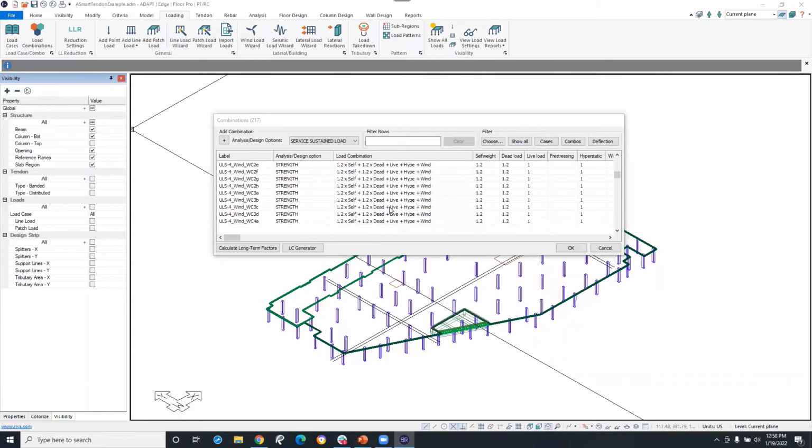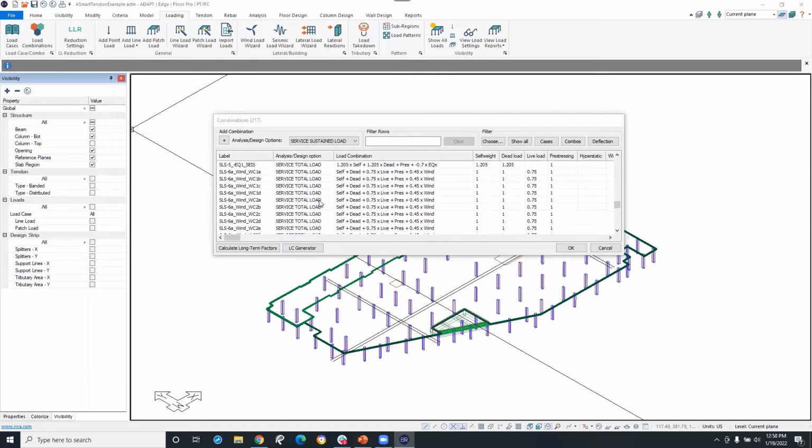And so we can quickly scroll through here, and you can see we start using all of those no code check wind combinations within these wind combinations, and rinse and repeat, right? And you can see all of these appropriate factors applied, and even within our seismic being adjusted as well for our SDS and all of that good stuff.